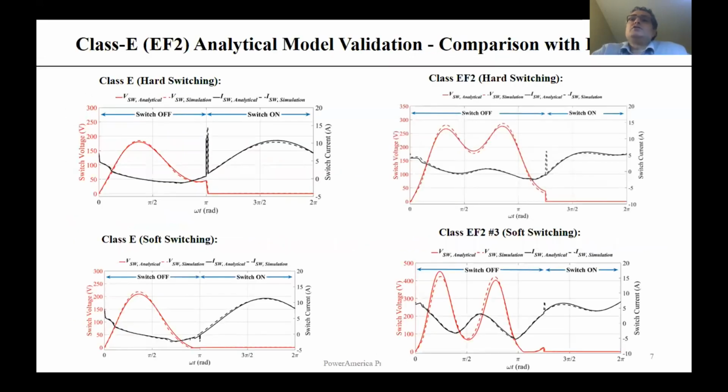An analytical procedure for calculating inverter signals is successfully derived for Class C and Class EF2 inverters. The waveforms generated that way demonstrate an excellent resemblance with the SPICE results. This slide shows the waveforms for hard switching and soft switching conditions in Class C and Class EF2 inverters. It illustrates the excellent matching I was talking about. Moreover, it takes only a tiny fraction of time to calculate these waveforms compared to the time needed for the SPICE simulator.